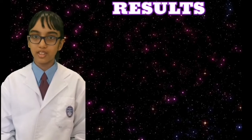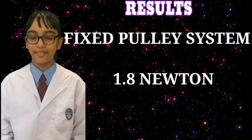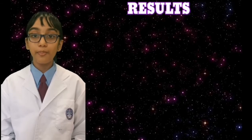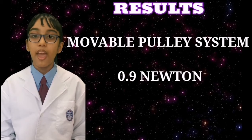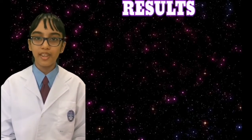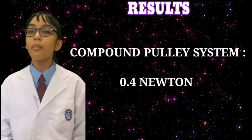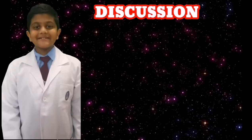For the fixed pulley system, the average reading was 1.8 Newton. For the movable pulley, it was 0.9 Newton. And lastly but not least, the compound pulley system, which is 0.4 Newton. Those are the average results.